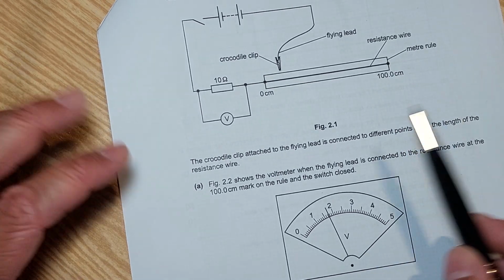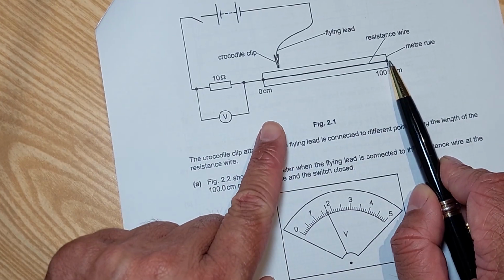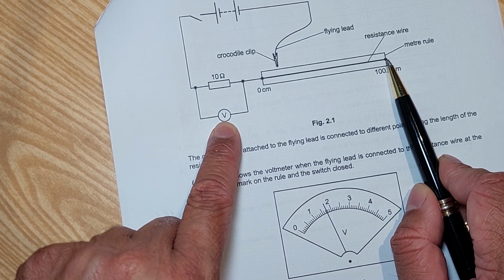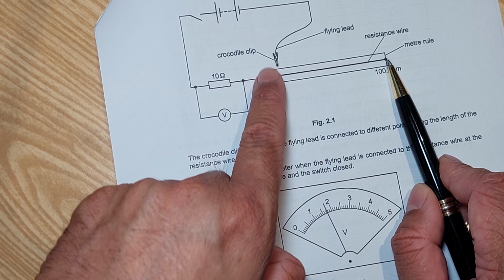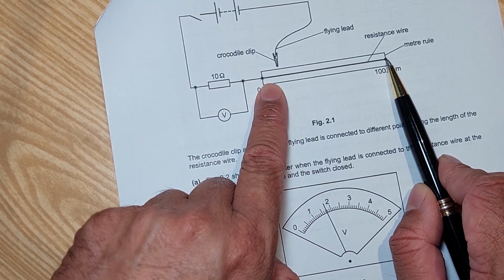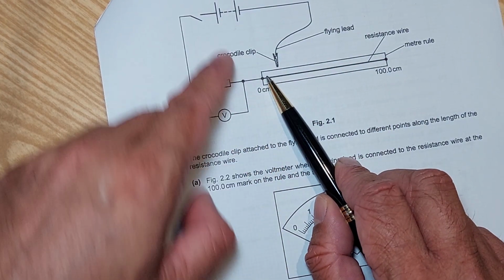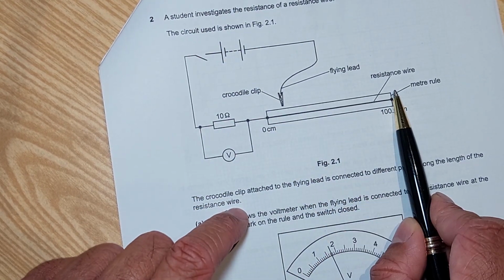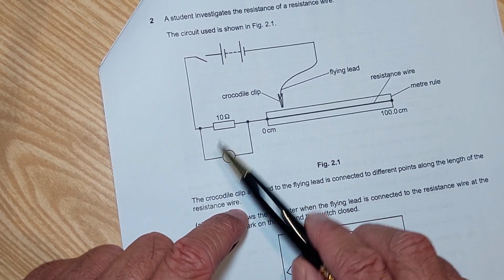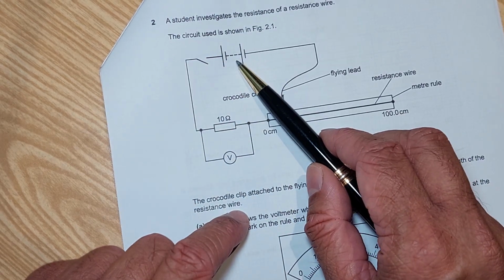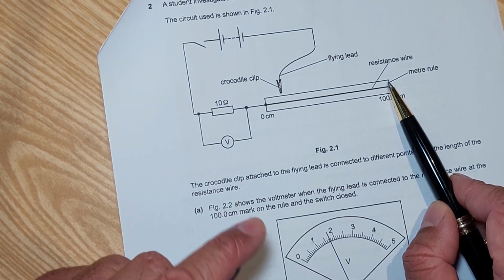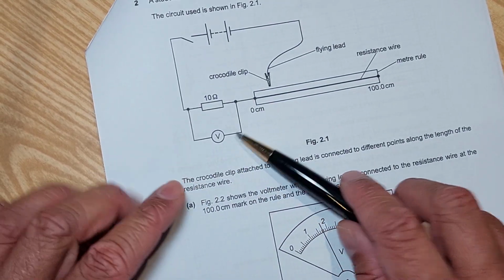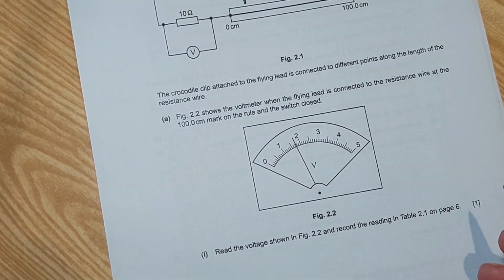So that is kind of like maximum resistance. Now, if it was over here, the voltage that we'll get over here would be a smaller voltage, because most of the voltage is across this now. And if it were here, we would probably get the full voltage of the power supply over here, because there's no resistance. So the entire resistance is over there. So this voltage would represent the actual voltage of the motor. But when it's over here, it gives you a maximum voltage across this, so minimum voltage over there. So that will be the smallest. But anyway, he's not asking us that.